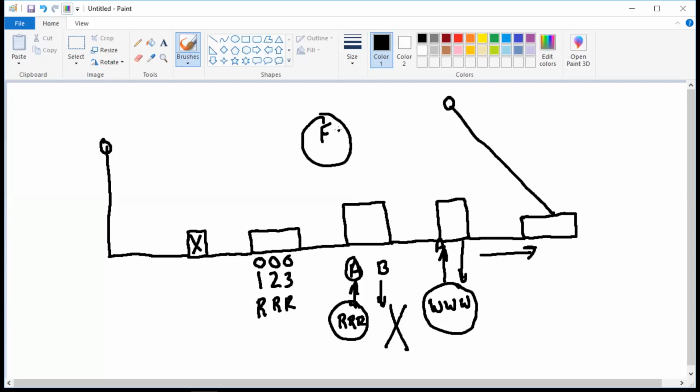So every fault indicator that sees fault current is going to trip. So if the fault happened here, will these indicators see it? Usually you don't put them on both sides, you put them on the A side. Did these indicators see a fault? Yeah. Okay, did these indicators see a fault? Yeah. And of course the fuse is blue, that's our other fault indicator right there. So all of those saw a fault.